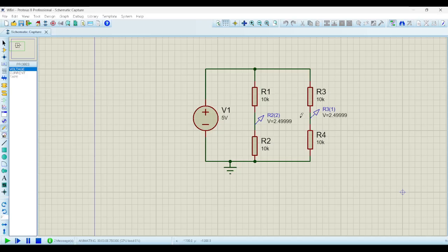In this configuration, now I have the Wheatstone bridge, right? If you remember, the Wheatstone bridge was 4 resistances. They are connected in series, these two connected in series, and they are in parallel, right? And I can measure the voltage difference here, right? Let me add here